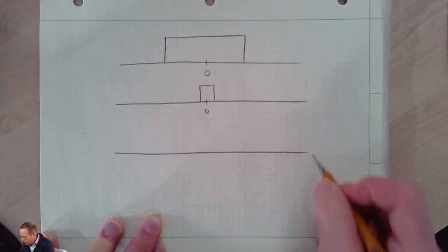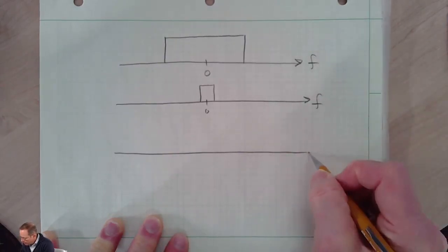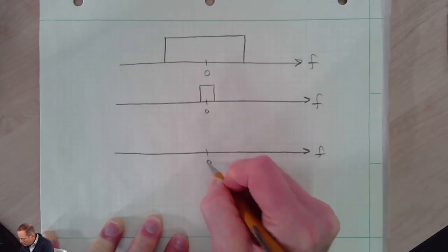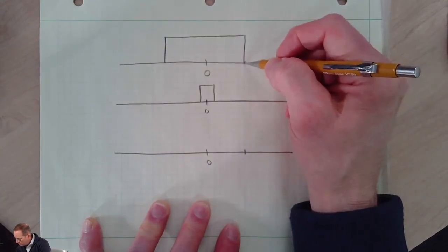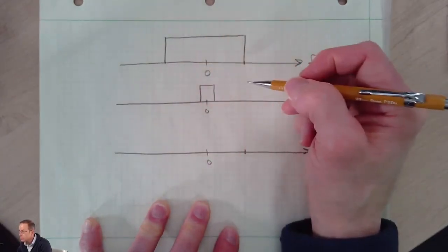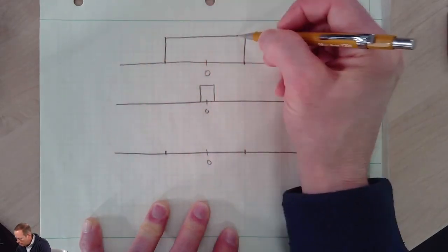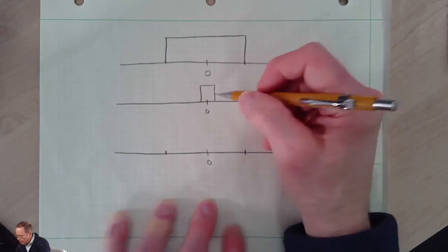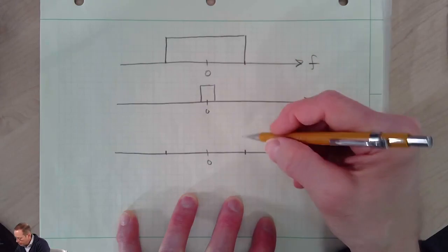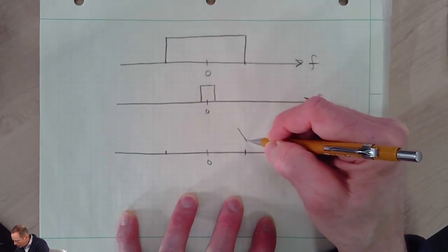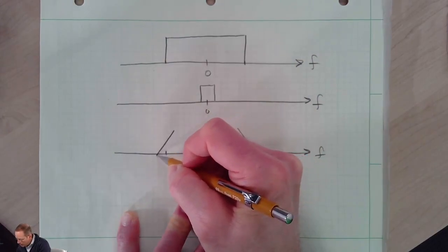And you can imagine that when we convolve these two, remember this is in the frequency domain, when we convolve these two functions together, what's going to happen is right around this frequency where the wide rectangle function transitions from stop band to pass band, or from pass band to stop band, when we convolve this small rectangle by the bigger rectangle, what's going to happen right here is we're going to get a linear roll-off between pass band and stop band.